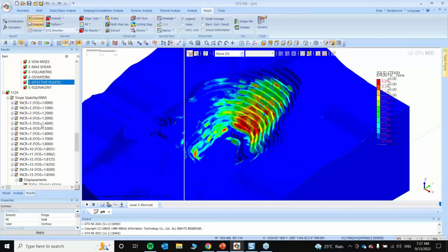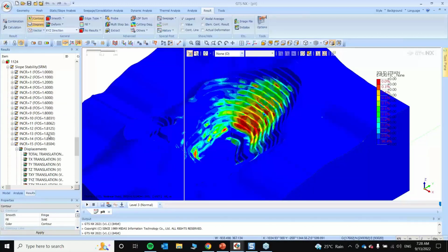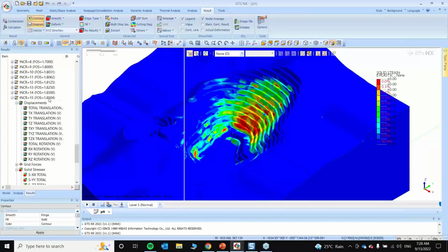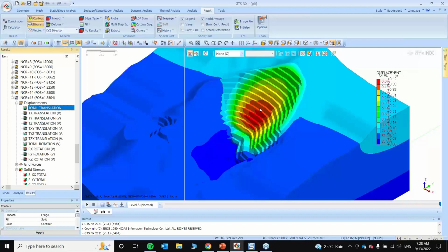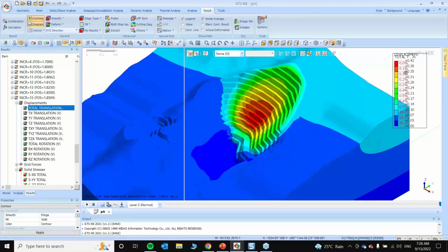So now, if we go to check the slope stability results, the factor of safety was 1.85. If you can see the total displacements, that area in the non-linear static that showed the maximum concentration of the plastic and shear strains, that is the critical area in here. So remember when I said that the results for SRM you will get is just before failure. You can see the displacements now, 42 centimeters. This area will pop up 42 centimeters and then it will completely diverge. Okay.